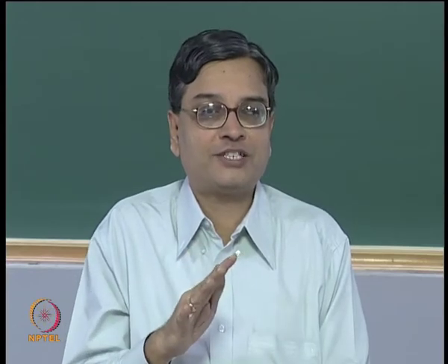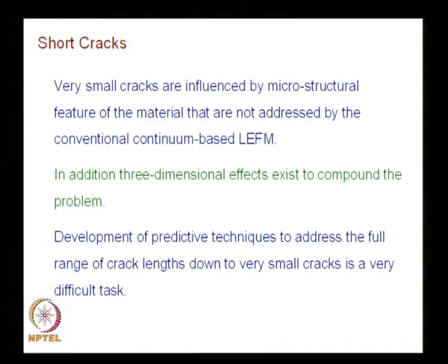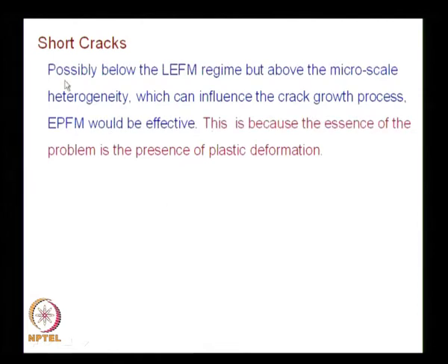You develop linear elastic fracture mechanics, so that we have a comfort zone, we understand reasonably long cracks, how do they behave, we are able to solve certain class of problems. So, that is only limited knowledge. Any predictive technique to address the full range of crack lengths is very, very difficult, and what we could do is possibly below the LEFM regime, but above the micro scale heterogeneity which can influence the crack growth process, EPFM would be effective.